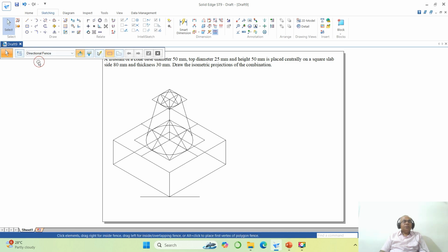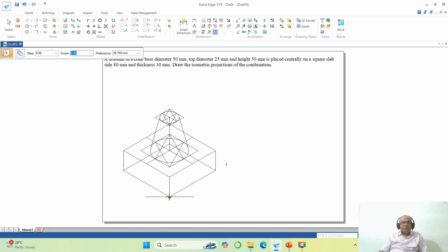Okay, now you go for scaling. So go to scale, select this entire drawing, take the endpoint, make it 0.816. Okay, then you go to text, here take the font size as 3. So here you write ISO scale used. Okay, then I need to go for